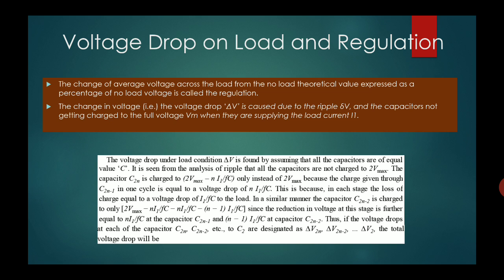Okay, so we'll talk about voltage drop on load and regulation. Now first we have to understand what is regulation. The change of average voltage across the load from the no load theoretical value, expressed as the percentage of no load voltage, is called regulation.